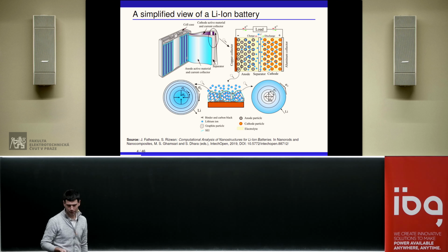At both parts of the electrodes, there are the current collectors, and the electrodes are composed of porous material, which is filled with electrolyte. So for example, during discharge, the lithium ions, cations, are released or de-intercalated at the anode. They move through the electrolyte, through the separator, into the porous material of the cathode, and then they are incorporated into the solid material of the cathode again.